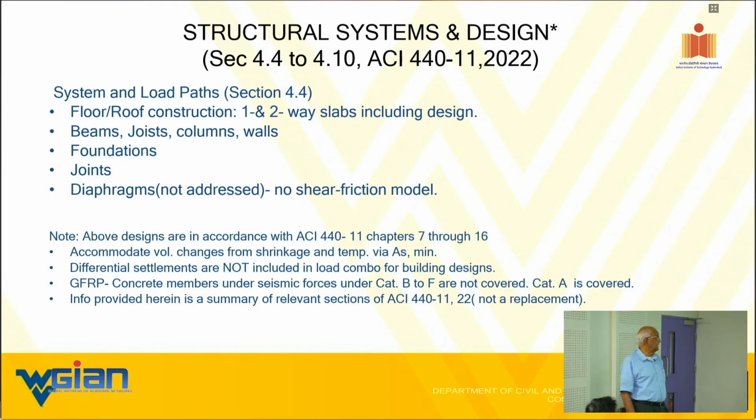They accommodate volume change from shrinkage and temperature through a minimum amount of FRP reinforcement. I'll define what that minimum amount is. Unlike the steel code, which is a 0.018 times A_s type thing for temperature and shrinkage, this is a little bit more involved than that. I'll explain all that as we go through the theoretical part, and again when we go through the design part.